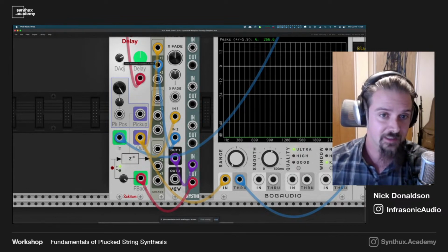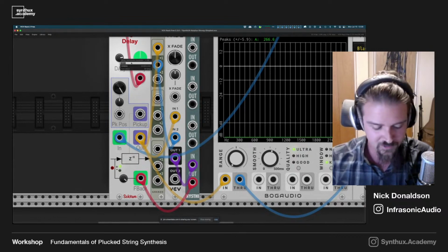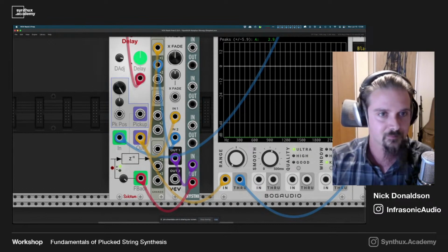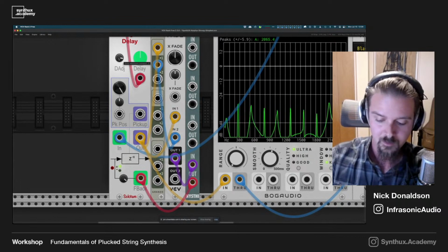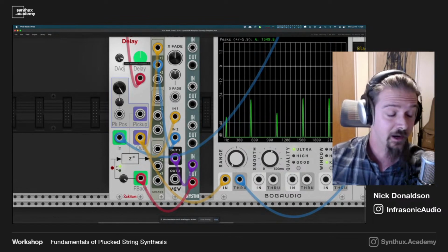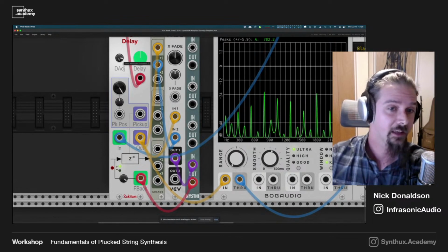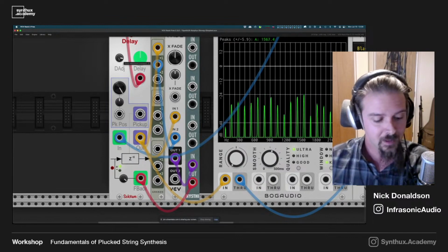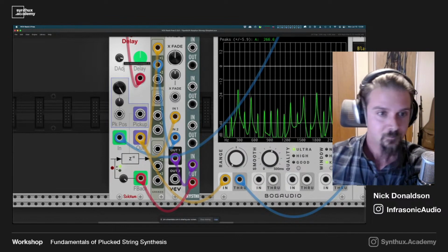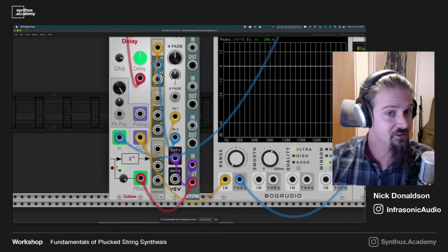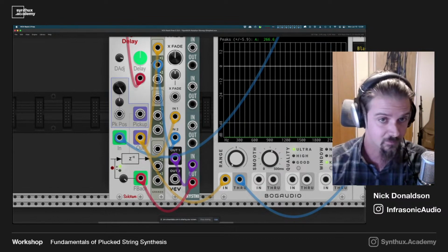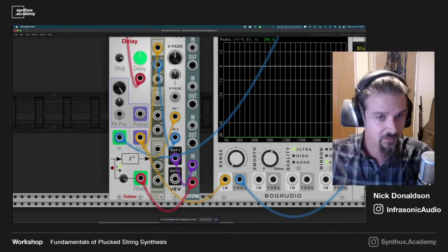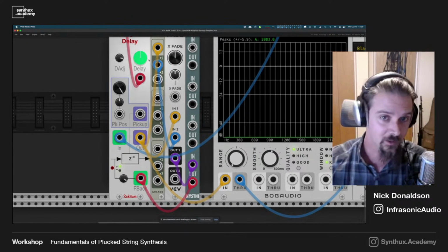If I don't set it to that, let's say I set it to, and it's fractional, by the way, so you can set this to, it doesn't have to be an integer. Let's say I set it to -2. Now you can hear it's out of tune, right? As we go up, it starts to get flat. That's because this additional delay is actually extending the actual net delay through the feedback loop by 1 sample per module, and this compensates for that.